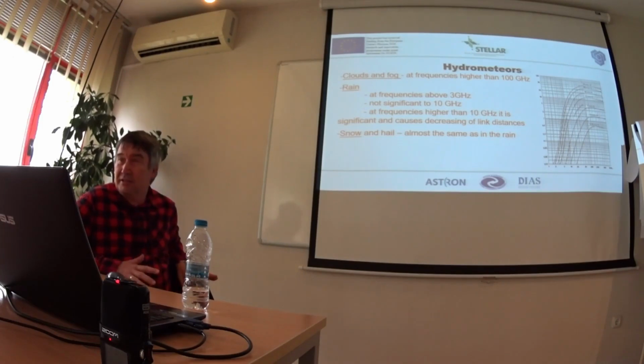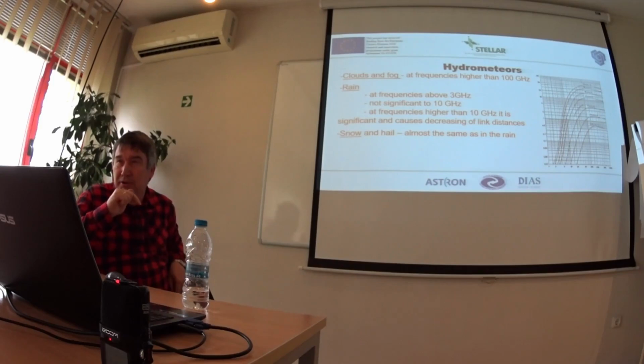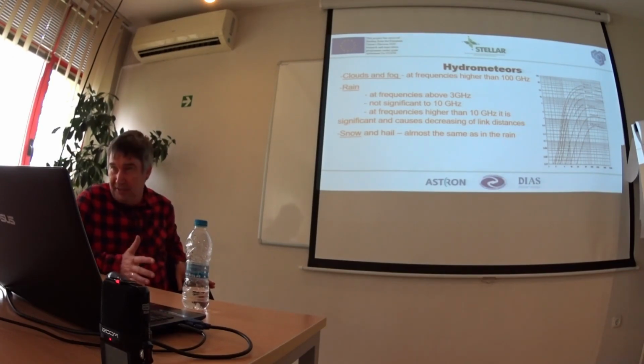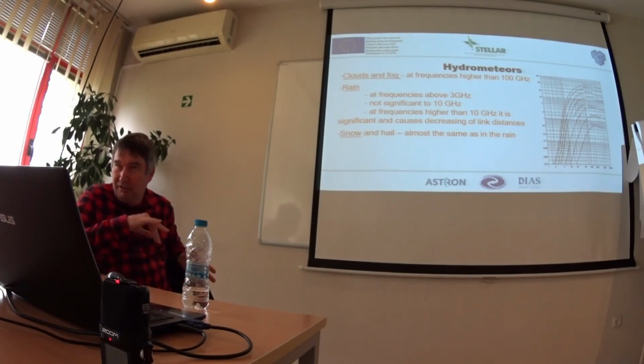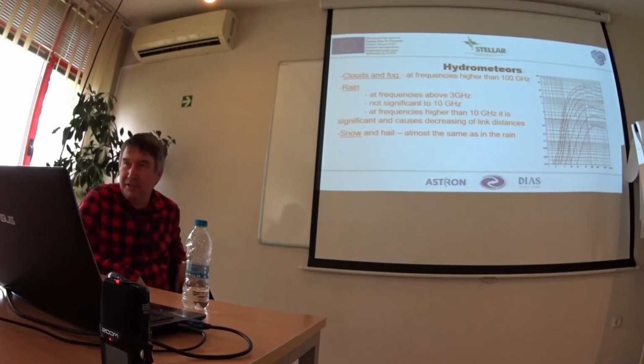To 10 GHz, it is not significant, it is small, but when we calculate some radio link, we have to take into consideration rain attenuation. But for frequencies higher than 10 GHz, it is very high for heavy rains. For light rains, it is not so high, but for heavy rains, it is a problem.